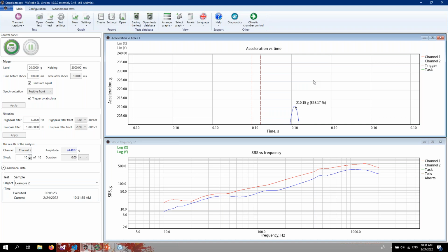I think you can find the maximum amplitude value by your sensor sensitivity. For example, our RLC21 has the maximum values of 10 volts and 10,000 picocoulomb on the channels. So you can calculate the maximum amplitude value by dividing this value of 10 volts or 10,000 picocoulomb by your sensor sensitivity, and in that case you'll get your maximum amplitude. So I think that's the answer.